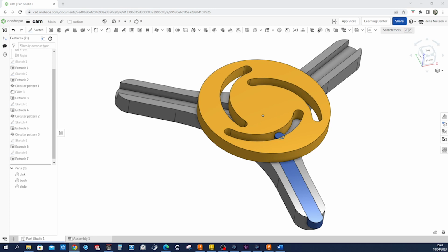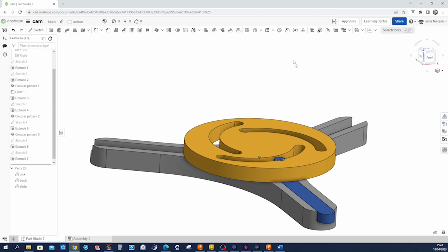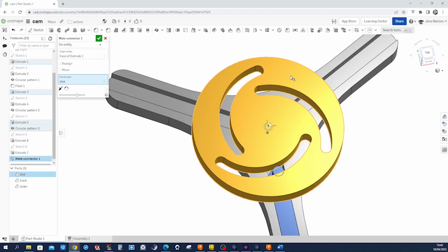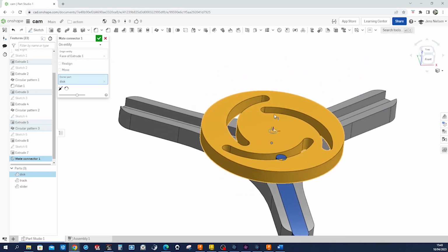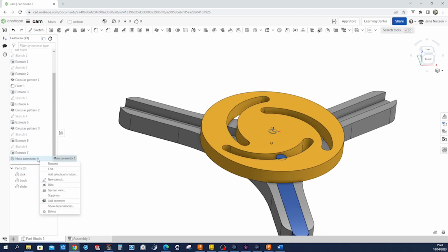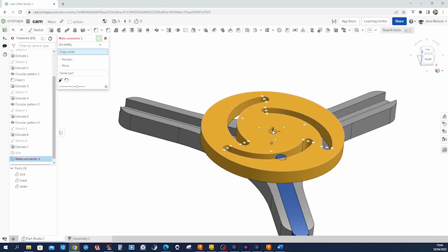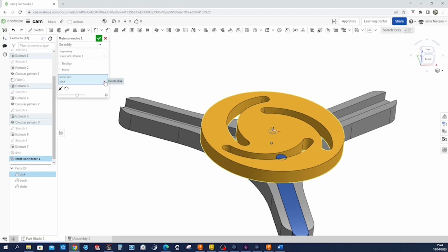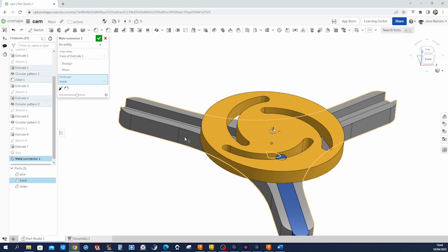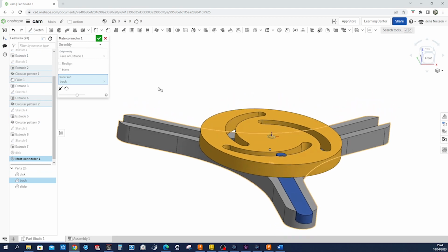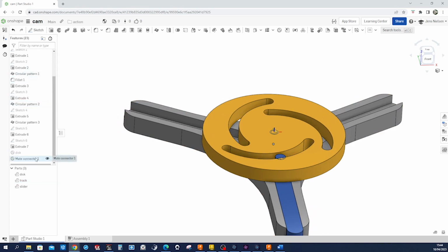And now let's define some mates in the Part Studio still. So first is the disk mate. Take that, go on that face, coincident with the origin, all right? Z-axis going up. All right, let's call that disk. And hide that. And take another one of those here on that same face, that same position, but the owner will be the track part. So let's call that track.